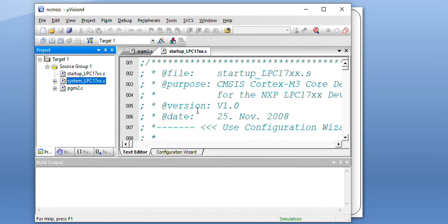So if you are working on some other platform, like an STMicroelectronics Cortex M3 processor, then you cannot afford to use this library. This library is intended to be used in the NXP environment, so it is for the LPC1X series. And there is one more file which is a system file. Even this is your CMSIS file. I hope you're clear with the startup file.